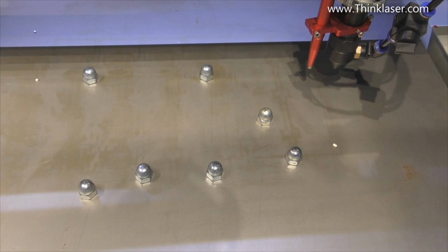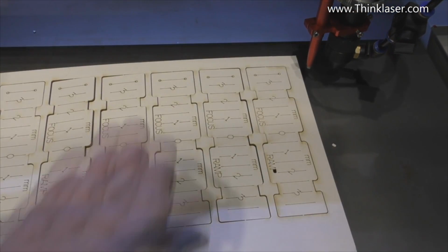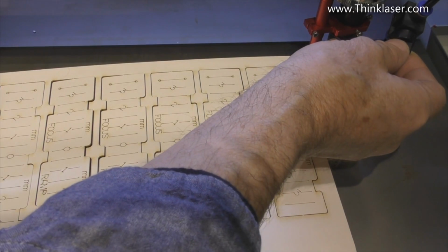So there's something about the setup of the machine that you really need to make a note of if you're doing cardboard, for example. Make sure you cover the bed and you get a linear airflow across your job. Turn off the air assist.